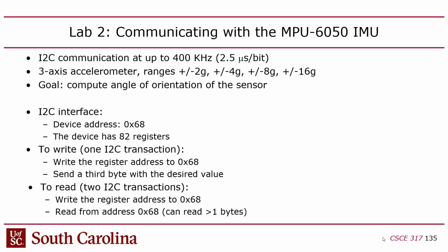That's the goal, but we want to do it by communicating with the IMU using I2C with bit banging, which is software-controlled I2C, as compared to using the hardware I2C that's built into the ESP32. Normally you wouldn't do that. You would just use the hardware I2C, but we're doing it for teaching purposes, so you can get some experience using the oscilloscopes for testing.